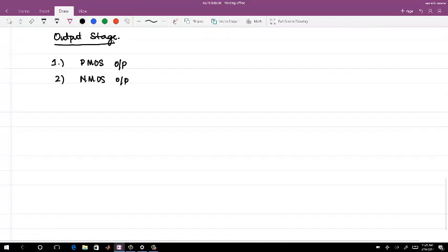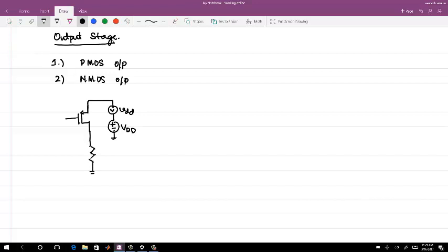Okay, so for the PMOS output, any noise is modeled as a small VDD on this, on top of whatever fixed supply voltage you have for the PMOS, and I'm modeling the equivalent resistance of the VCO as load RL. This is the output VCO node, which is Vs, or let me start calling it Vout.